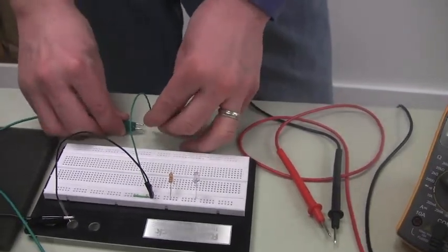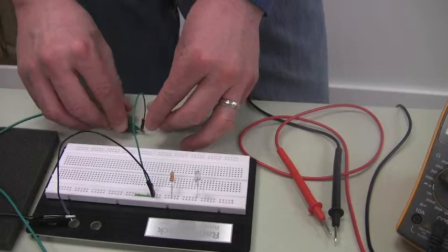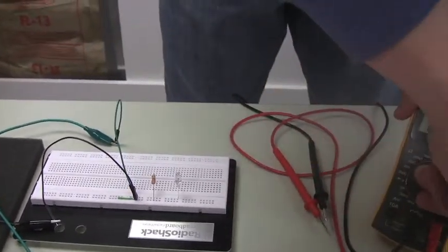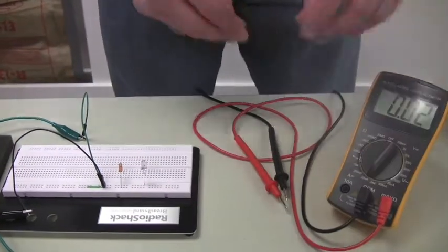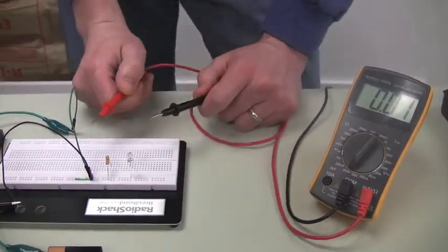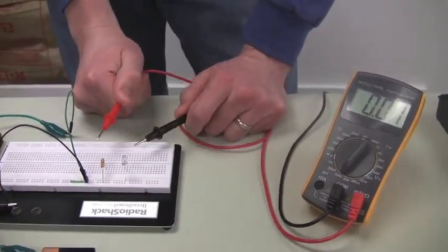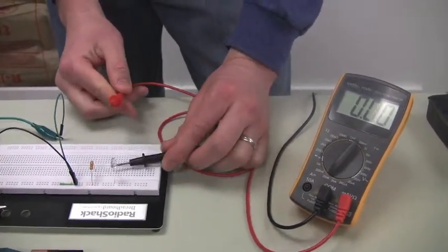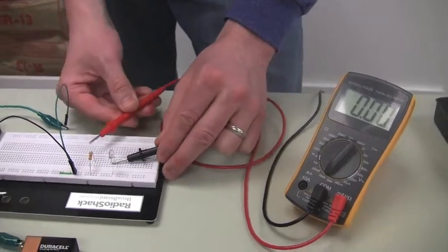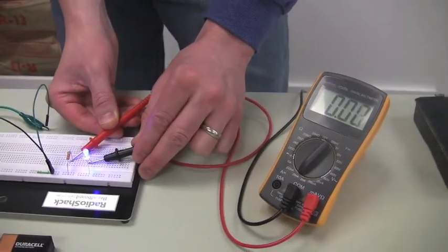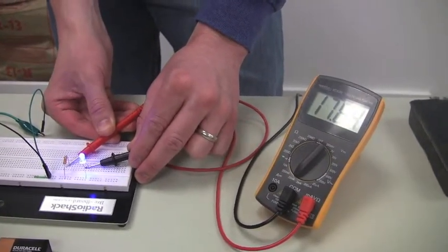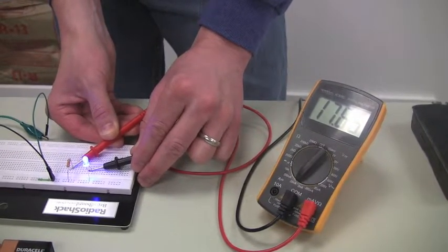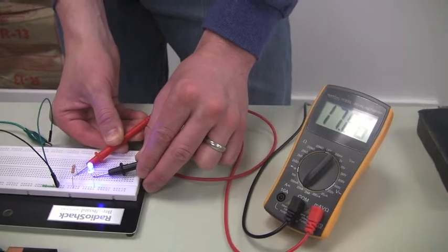All right, we'll hook up the supply here. And now I'm going to use my meter to complete the circuit. If you remember from the multimeter episode, we want to put this in line to measure the current and see how much current is going to flow through our little circuit here. So I'll put that there. I'll put that there. It'll light up. And you'll see there we're right about 17.65 milliamps. We're just under 18 there.